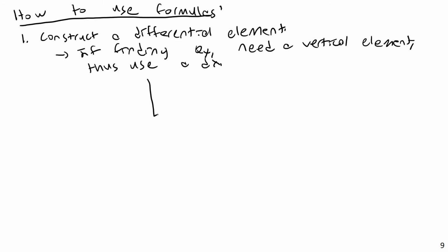So if you are trying to find the centroid of just a curve like this, you would have a dx here, and then some value for the height. In this case, this would just be the value of the function at x, and then you'd have a distance from the y-axis of just x, or x bar. Sometimes you also see it described as x bar in textbooks. But there's, of course, innumerable ways to describe these things.